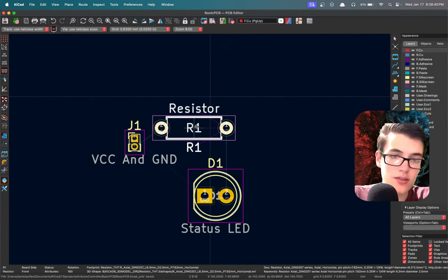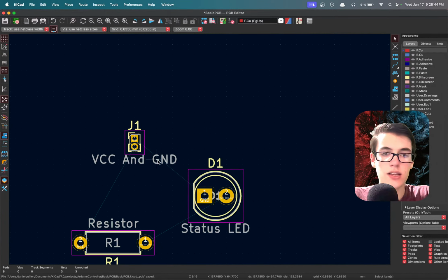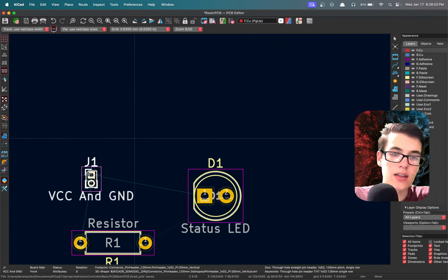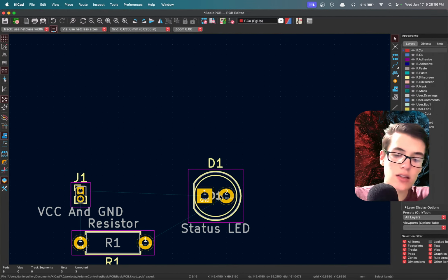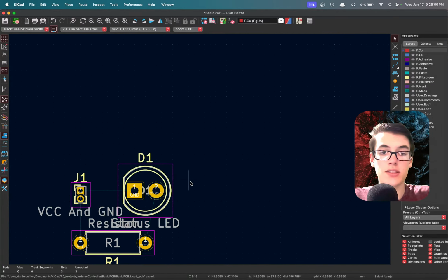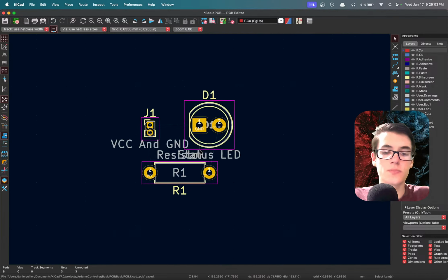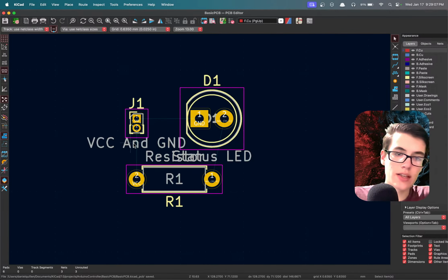And I actually just noticed they're also crossing down here. So I think the triangle should be like this. VCC to VCC, here to here, and ground to ground. Yeah, that should be right. Now there's no overlapping. So then we can kind of arrange these how we want to make it look a little better and be more compact, because obviously a smaller PCB costs less. So this seems like a pretty good arrangement.